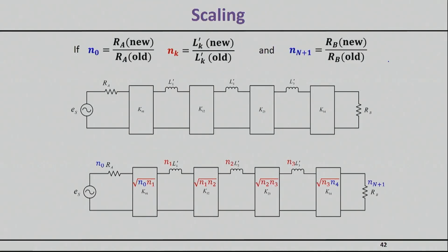Now, a few other things that you should note: it's not only the case that we want to scale the impedances. For example, the most common impedance scaling is we start from 1 ohm at the input and the output in the normalized impedance domain. We synthesize our filter in the 1 ohm domain, and then we scale to whatever impedance we actually want. Usually, that is 50 ohms.